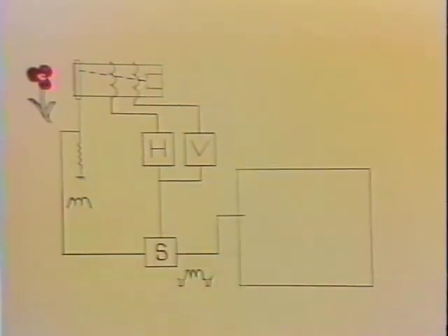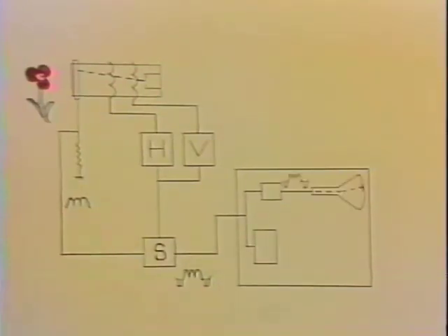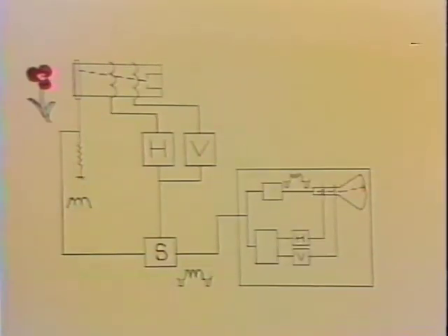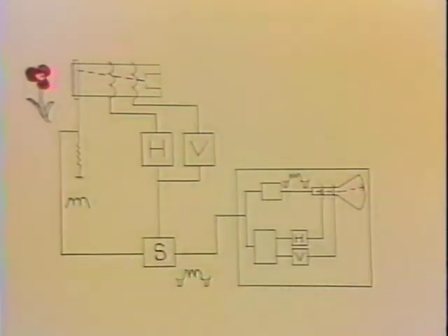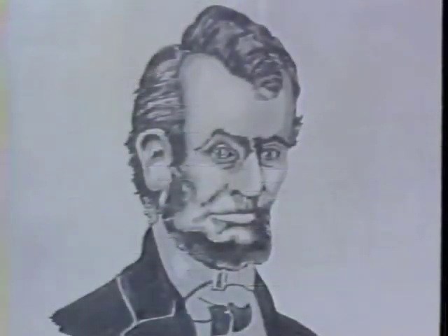The composite video signal enters a monitor or television set. Here, the sync is separated from the video signal. The video and sync are used to vary the brightness of the beam, and so produce a picture on the face of the tube. The sync pulses are used to drive the coils around the tube neck, which cause the beam to scan the face of the tube. The result is an electronic picture written on the screen, which is a faithful reproduction of the original.